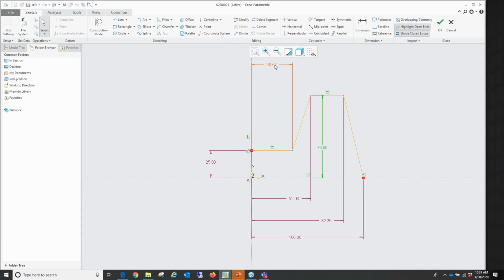And then the other dimensions I want to modify are these distances along. So I'm going to change this dimension here and make that 40. So for the first 40%, it's going to be 25. And then I'm going to make this dimension here 60. And then it's going to go from the 40% to the 60%, rising up from 25 to 75. I'm going to keep this here and make this 85. And then out to the 85% point, it's going to be that height of 75. And then at that point, it's going to start to come down to 0 at the end on here.